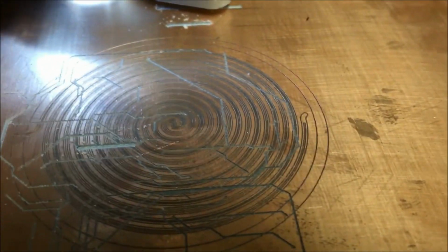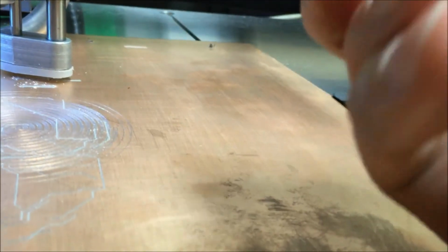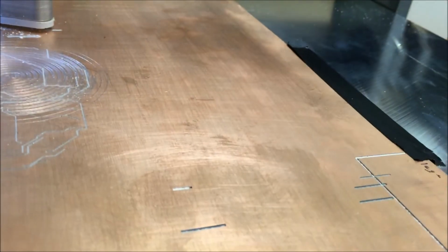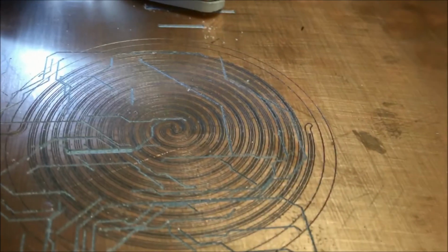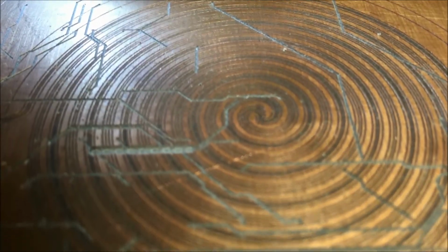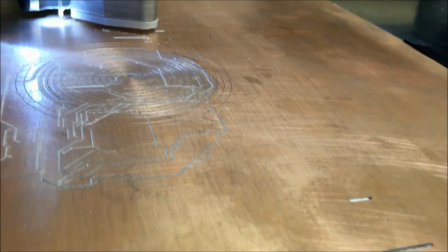And there's a visual in the manual to see what you're actually supposed to see. Let's see if I can find that real quick. The vacuum also should be on right now. The T-Tech guy said it comes on only when the machine's actually on, although it still does seem to leave some specks there. So I'm not actually fully sure if the vacuum is working, but I'm just trying to find the visual real quick, because there's a pattern that you can see in there to tell whether or not the cut depth is correct. No, it's here. If I can't find it, I'll just skip that for a moment.